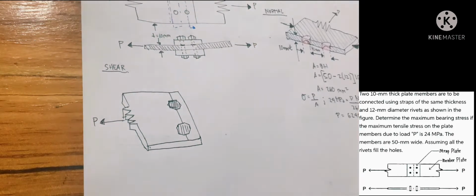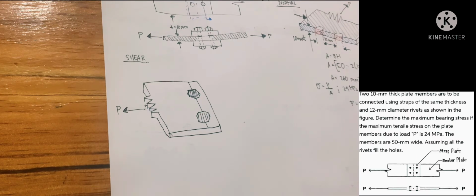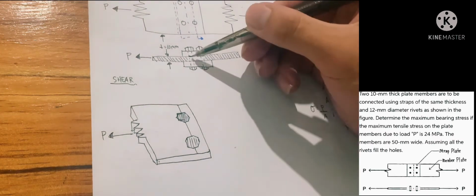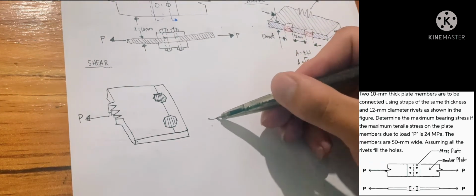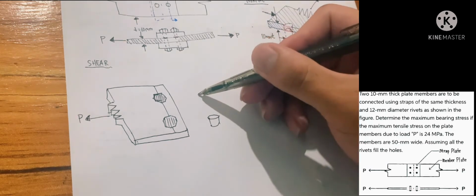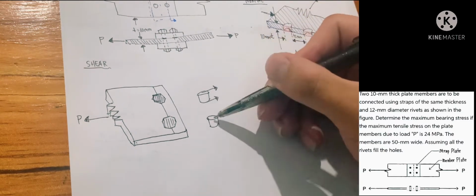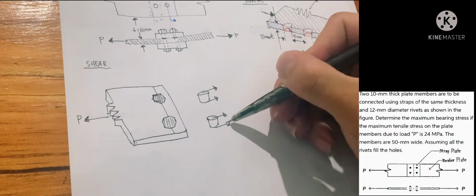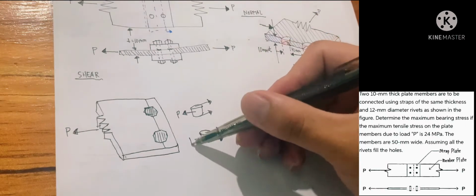For example, if we have the same 4 rivets, but the distribution would not be in pair, but there are 3 rivets on the left side and 1 rivet on the right side, the place where the maximum would be is at the 3, because when the rivet that does not have a companion would break, the other 3 would still hold.